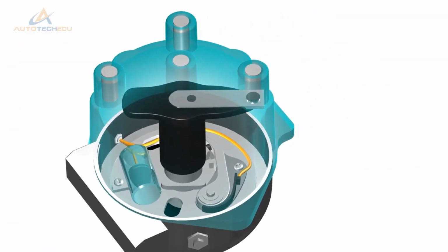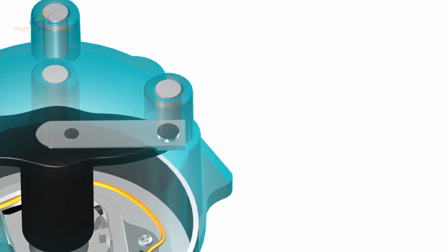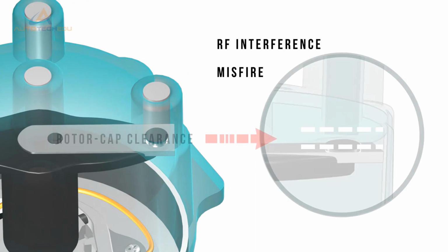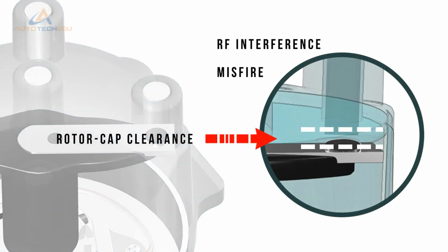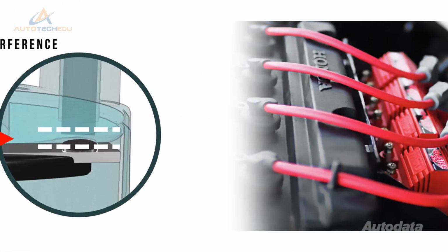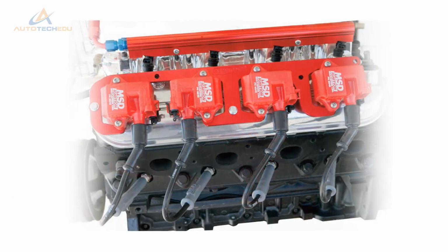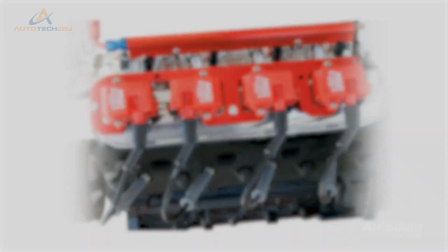Because there is no distributor and therefore no distributor cap, problems such as radio frequency interference and misfire due to excessive rotor to cap clearance have been eliminated. More ignition coils for the same number of cylinders allows for greater saturation time and more stable operating temperatures.